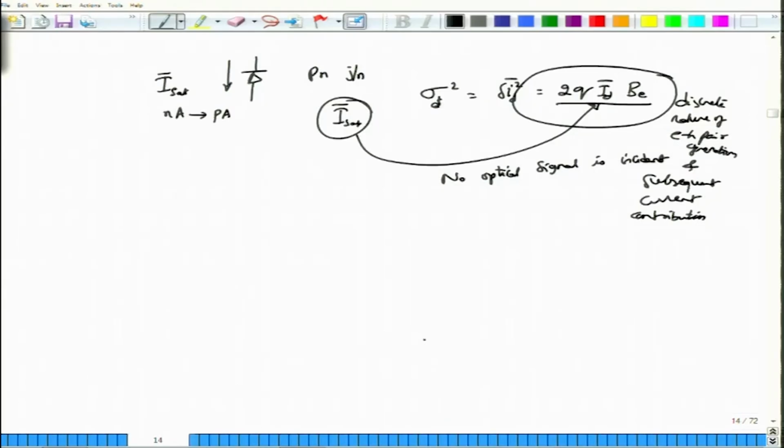Okay, so that is what the source shot noise is, and this is the detector shot noise, and these two are also present together. Of course, when there is actual current because of the light, then that would be added to the dark current, but this value is so small that you normally neglect it. Then there is another source of noise, and that source of noise is the load resistor that we actually keep, because the load resistors themselves are noisy.